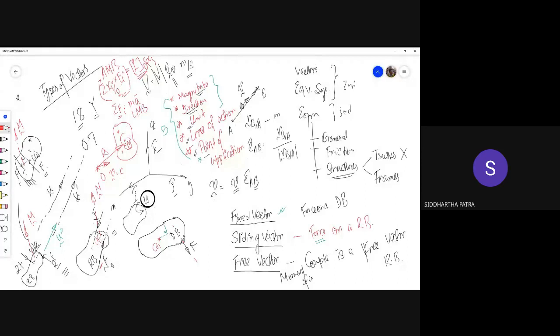These are the only two quantities that matter. That means the vector normal to the plane of application of these two forces becomes the direction of the moment, and the magnitude of the moment becomes simply the normal, minimum distance between the two forces times the magnitude of one of the forces. That's what matters.